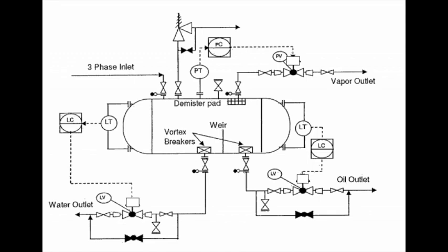It's a level transmitter. So the level of the first liquid is measured, then it is sent through electric current to the level controller. Here, as you can see, the level controller is shown in the DCS. Then the signal is sent through electrical signals to an electric valve to control the output of the first liquid.